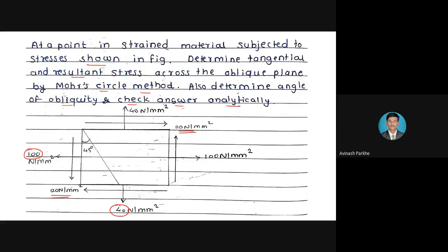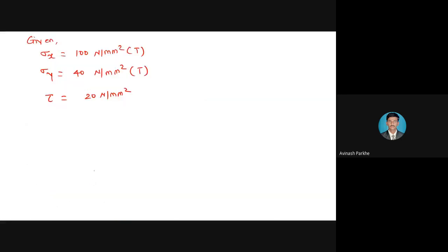Now, please tell me, according to the sense of the shear stress, whether we have to take that shear stress as positive or negative. Apply the sign conventions; we have figure A and figure B. Positive. The shear stress is positive, because of the sign conventions I have given. We also have one statement: if the shear stress is rotated in the anti-clockwise direction with the major principal plane, then we have to take that shear stress as positive by the sign conventions.